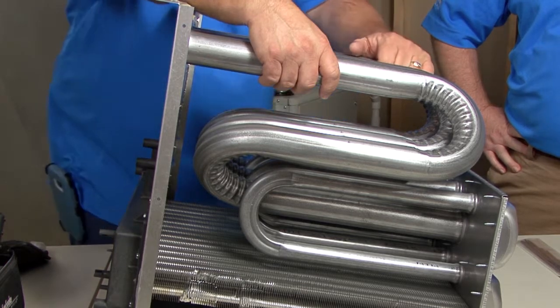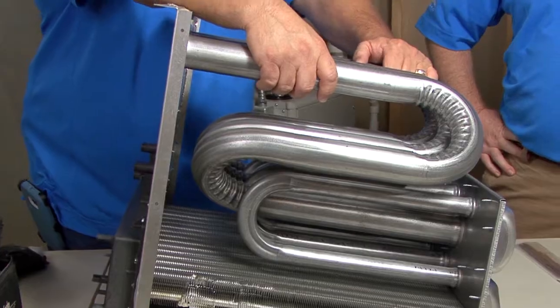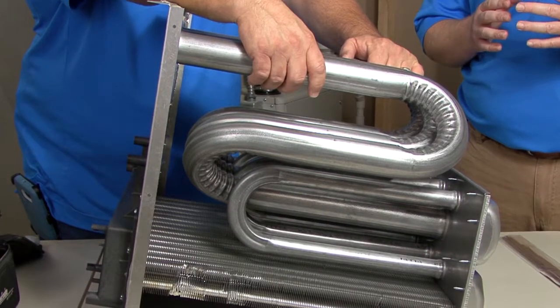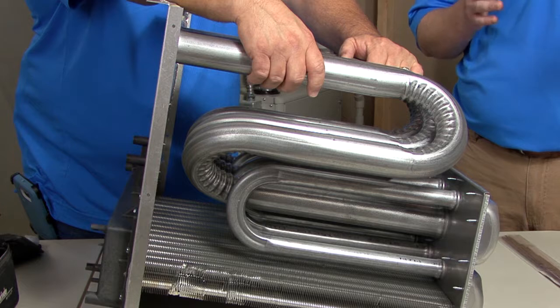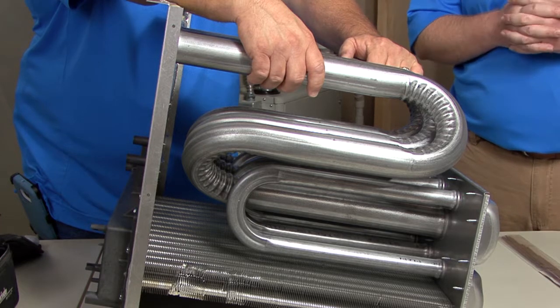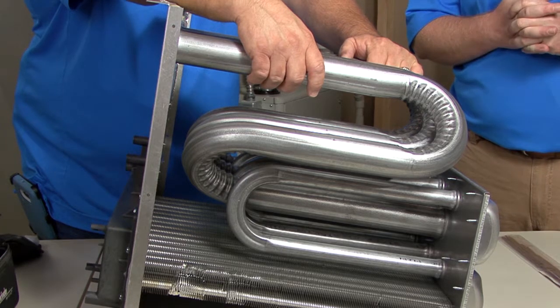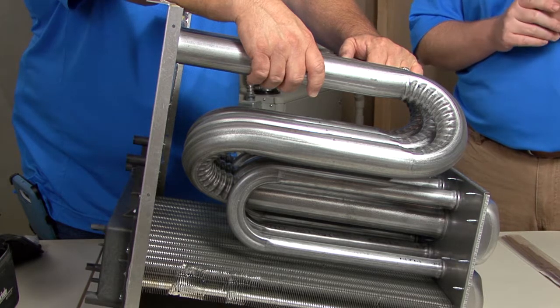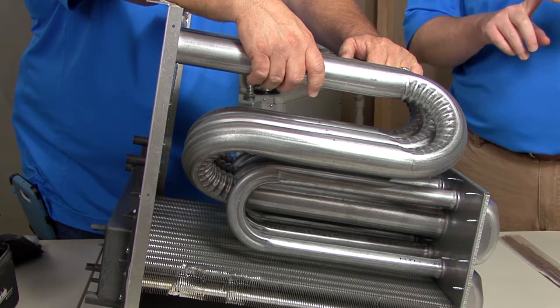One of the things, too, that I want to point out is that when you are performing a smoke test on a heat exchanger, maybe much like this one here, let's say that maybe the smoke test was a little inconclusive. Maybe through a process of elimination of a couple different methods, maybe I could see I had a little bit of flame impingement beginning to happen, or maybe I could see that I was starting to get a little bit of rollout or something like that.